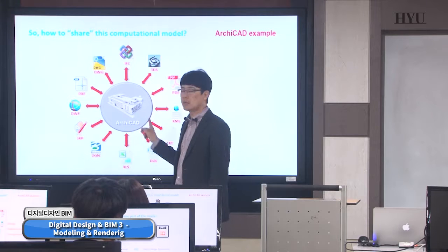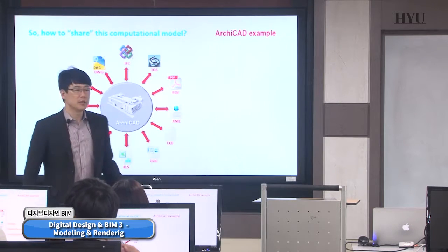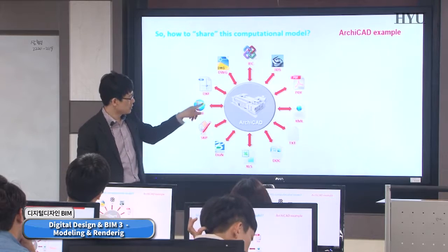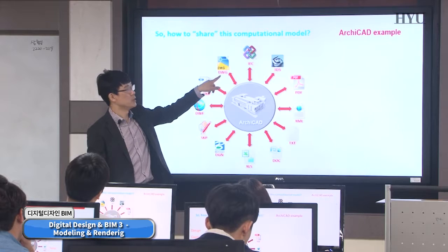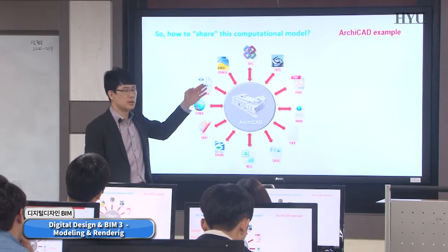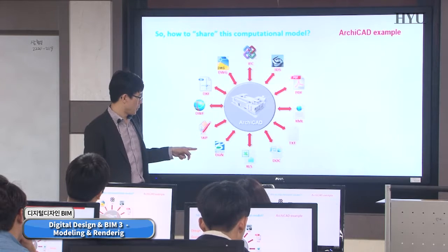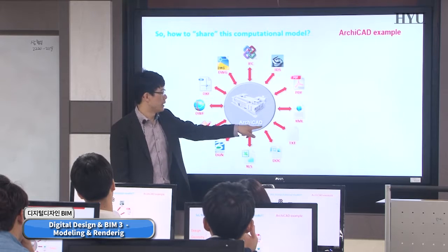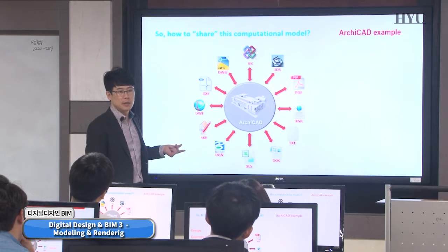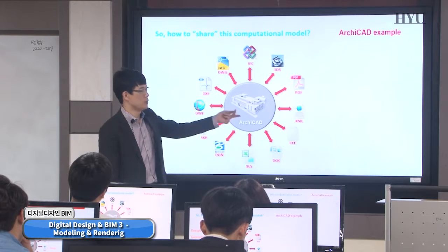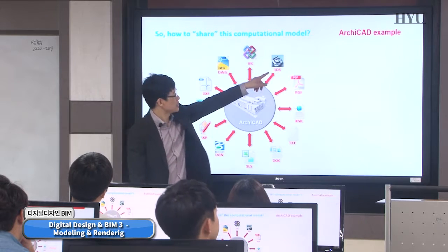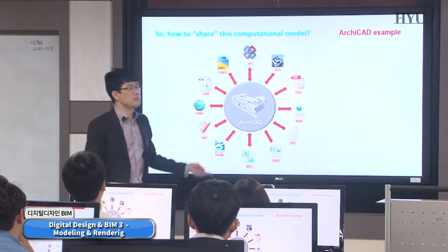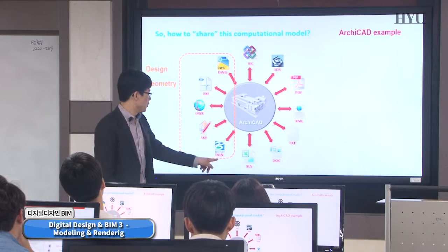There is an ArchiCAD model, the ArchiCAD Graphisoft application, a Revit-like BIM tool. This one has functionalities to import and export several file formats like this, such as DWG, the AutoCAD file, DXF, DWF, some CAD files, and SketchUp models. Even the Bentley DGN extension file can be imported and exported by ArchiCAD. But unfortunately, the Autodesk Revit RVT file cannot be imported or exported directly. But 3ds, PDF, even text files, DOC Word files, and Excel files are all importable and exportable. So what are those files?